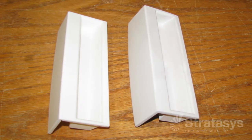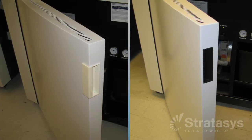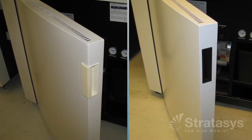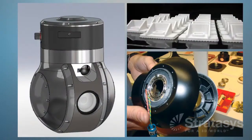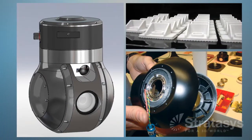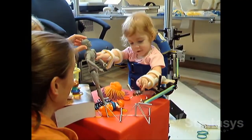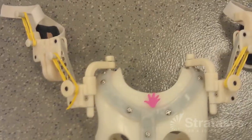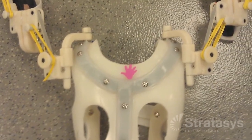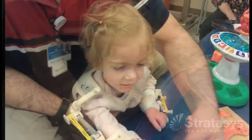Once the product has been validated and all component designs are frozen, FDM can be used as a bridge to production, making end-use parts while waiting for delivery of tooling and manufacturing equipment. For some of the more complicated geometries and customizable solutions, full production with FDM is the practical option. Since traditional tooling is aimed at production of a single design, FDM is an efficient and optimized solution for products that are continuously changing, either through product revisions or through order-by-order customization for products such as prosthetics.